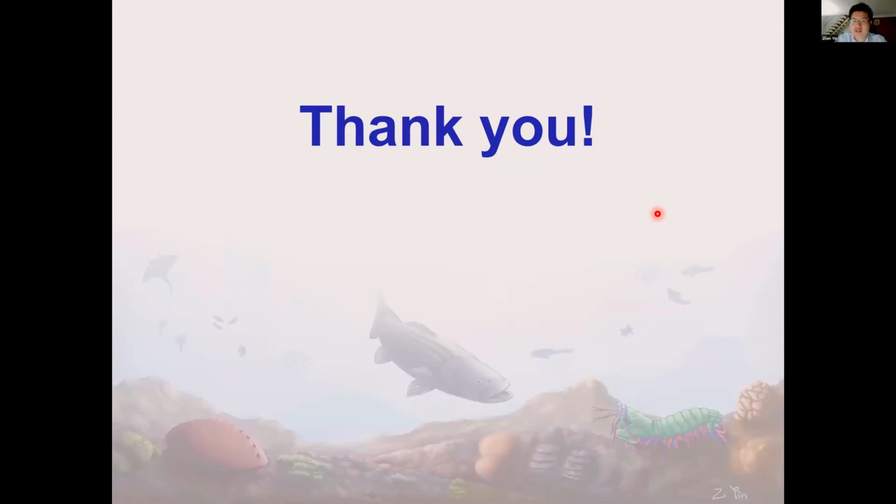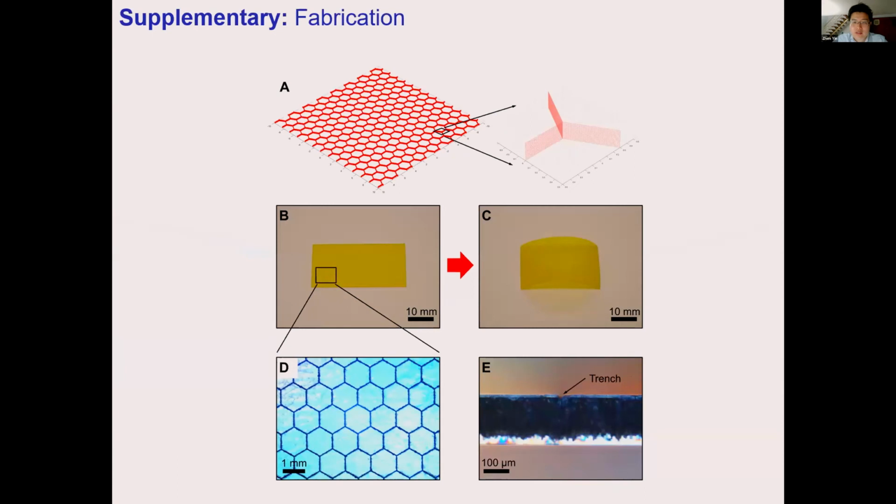Sure. I don't work in the area, but the idea is to create weak interfaces in the glass by etching specific patterns, is it? Yeah, it's not exactly etching, but it depends. Sometimes we engrave; I can show some pictures to better illustrate. Sometimes we etch a trench on the top of the glass layers, and then we mechanically separate them. Sometimes we engrave an area of micro cracks within the glass.